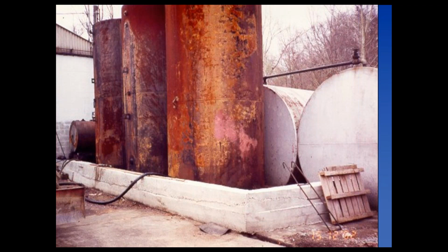There's a lot of problems here, but the biggest problem is one of the provisions: you have to use and operate a tank in accordance with its design requirements. There are 3 tanks here, and the key, as an inspector, what we always tell our inspectors, is if you look at the penetrations of the tank and the middle tank, and everything's in a straight line, including the lift for lifting the tank, that's typically an underground storage tank.